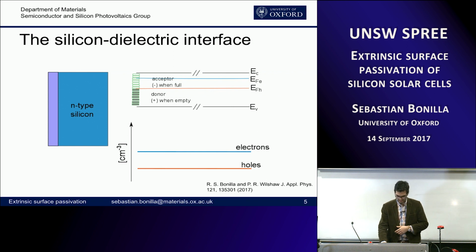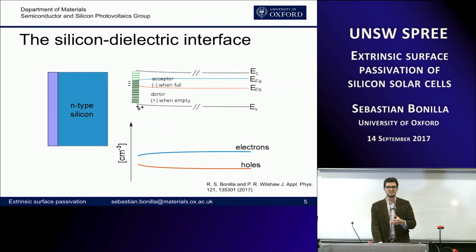So in this example here, for instance, if we have those Fermi levels as they're pictured there, what we know is that some concentration of those acceptor-type states will be occupied, so they will be negatively charged. And to compensate for that negative charge, we normally have a small space charge region at the surface of our silicon, which is a very normal phenomenon.